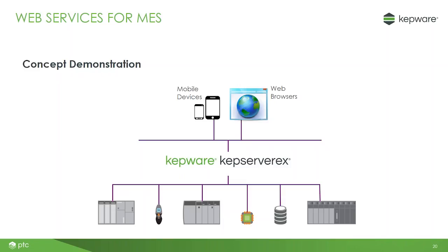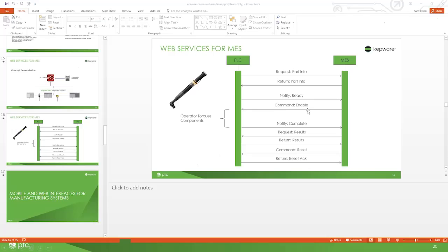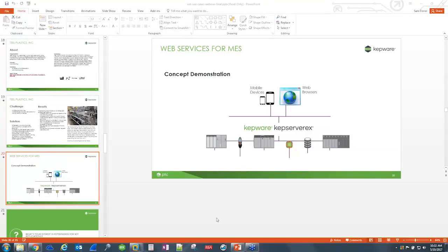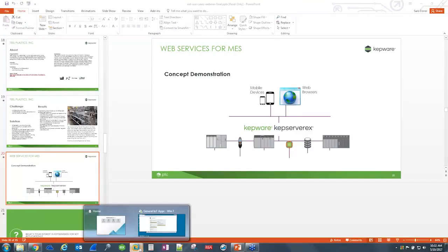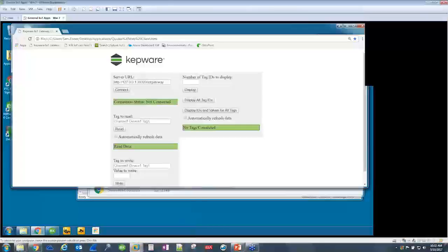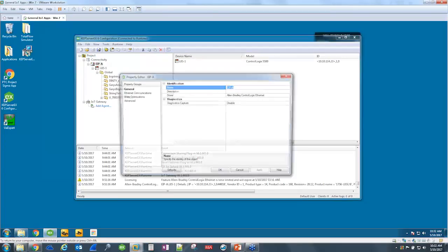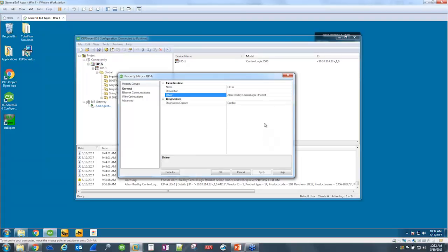So in leaning towards web, they really then found that they wanted web services as a point of interaction with Kepware. They evaluated leveraging software development kits to bring in different types of OPC standards and other standards, but there's nothing simpler than the baked-in library to Ajax, say, developing an HTTP request. We can do that right within a web page. In fact, I'll demo that just now, in a couple of seconds. So for them, being able to leverage HTTP made the point of interaction with Kepware incredibly simple, and it's something that could be completed within half a day. And then they can move on to the more critical aspects of the environment, which is really developing a good operator workflow in the context of that HTML client, that HTML page.